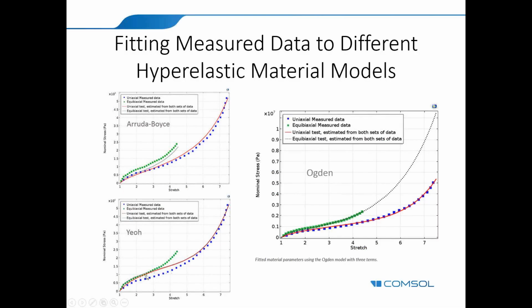It does not really fit our data so well in this case. For smaller values, it fits the biaxial data well, but for larger values of stretches, it fits the uniaxial data well, so not good overall. But the Ogden material model, as is usually the case, fits both the raw data perfectly, the uniaxial and biaxial both. And this is what you want. You want multiple experimental data to fit against your analytic curves.